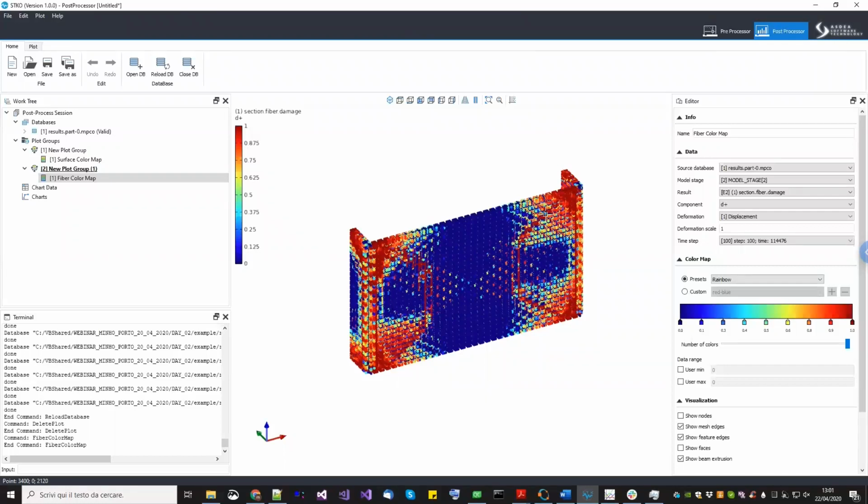From a practical point of view, I would always use the thick theory in any case, just because of one reason. The thick shell implemented in OpenSees has a special treatment for the out-of-plane bending that works both for thin and for thick shells. So in any case, yes, use the thick shell theory. Unless you know that you are doing a particular benchmark and you want to test the Kirchhoff law of shell theory, you can use the other. But I will always use the thick shell theory, yes.